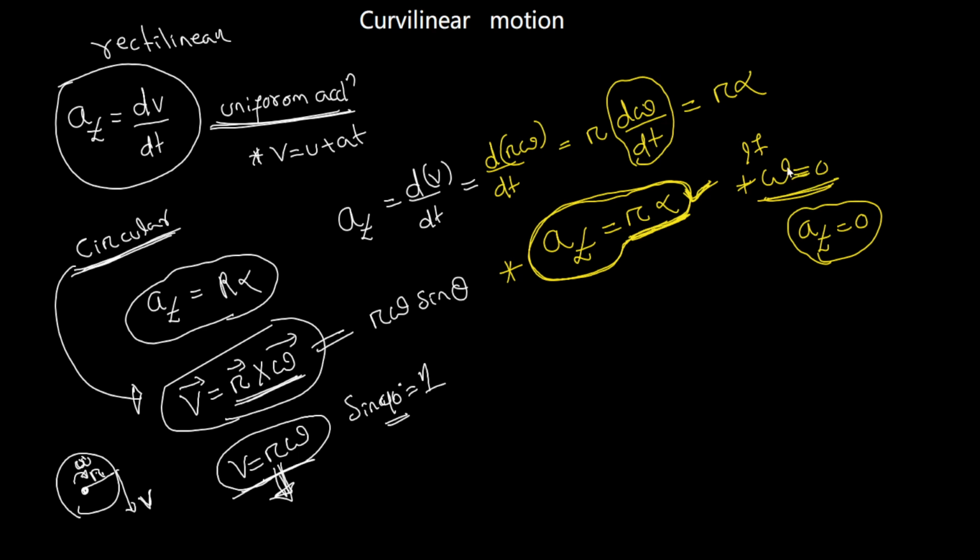Whenever there is a circular shaft in an engineering application rotating at an angular speed of n rpm, revolutions per minute, omega is written as 2 pi n divided by 60, in radians per second. This is the formula for omega when a shaft is rotating at a speed of n, having unit revolutions per minute, rpm.